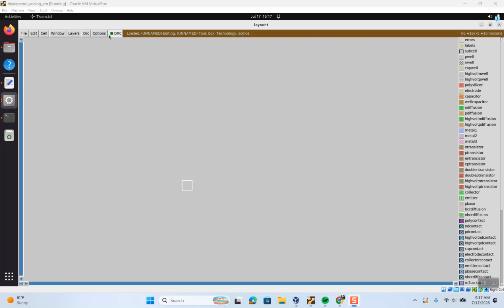So actually turn off design rule checking, because with a lot of the vernier scales, I'm doing things off grid, and I am violating design rules, which sometimes is inevitable. All right, so I've turned that off. If you don't, sometimes it crashes.